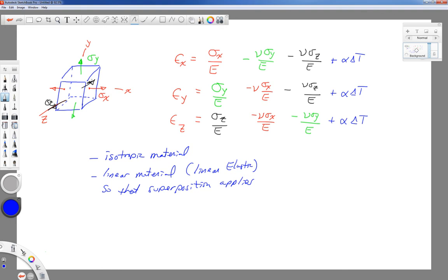Shearing stress that is on the x face and points in the y direction is known as the shear stress tau xy. It exists all the way around the block or the cube. We already know that shearing stresses have to be in a set to keep equilibrium. So we can calculate the shearing strain from Hooke's law in shear. Gamma xy would be equal to tau xy divided by the shear modulus G.